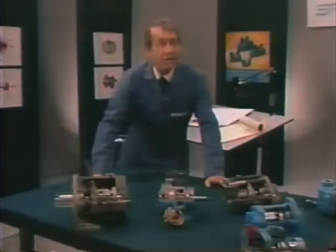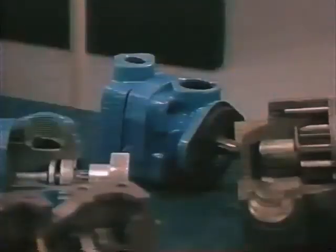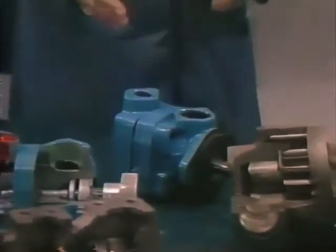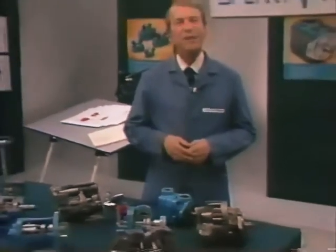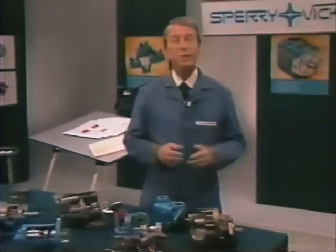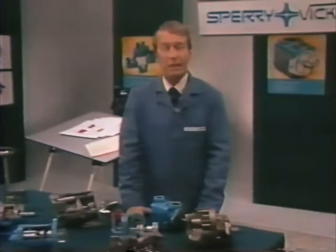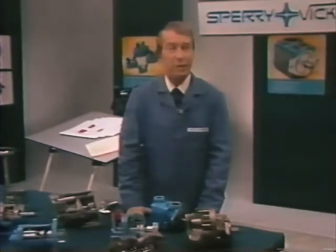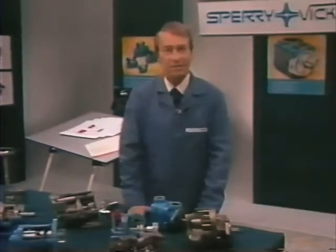The V104 is an extremely quiet and efficient pump, but its pressure and drive speed limitations of 1,000 psi and 1,200 RPM limit its use in many of today's applications. So, where higher pressure and drive speeds are required, as in most mobile vehicle applications, the Sperry Vickers Model V20, or square pump, is more apt to be found. With permissible speeds up to 3,400 RPM and pressure capabilities of 2,500 psi, it's well suited to many vehicle applications.